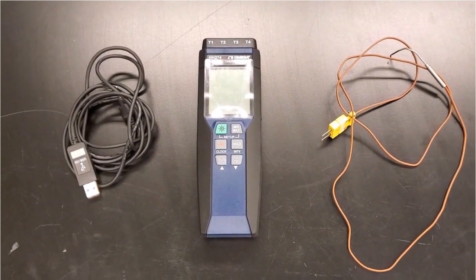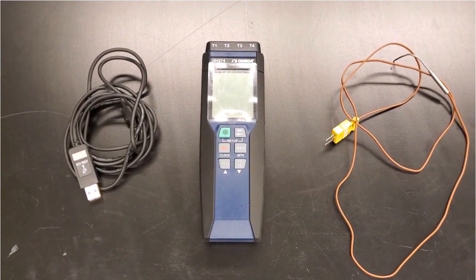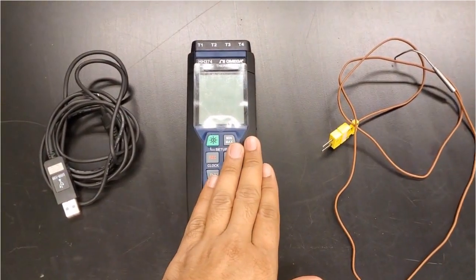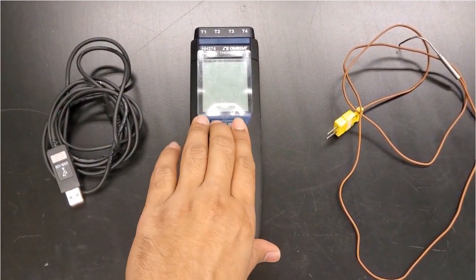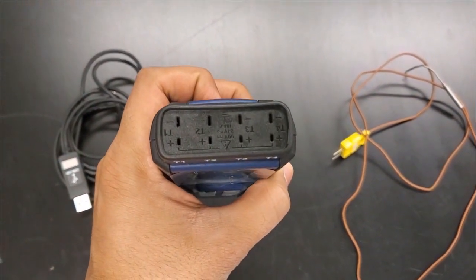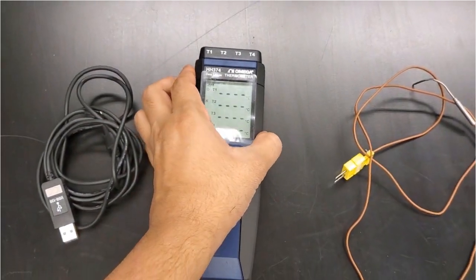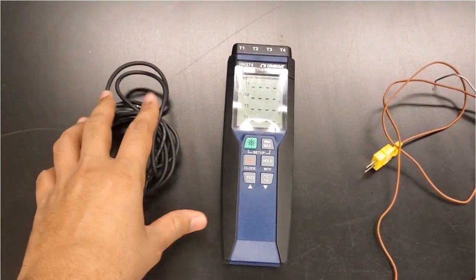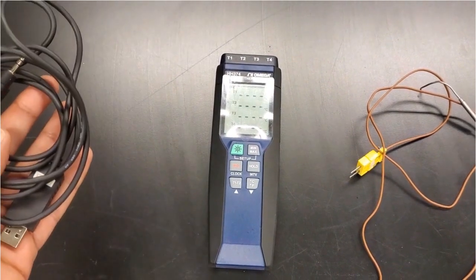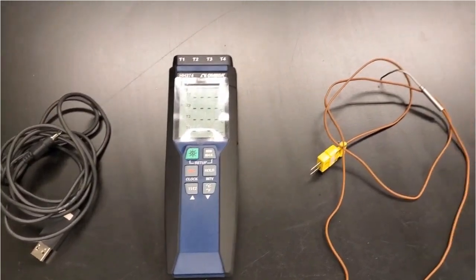This is the thermometer that we use in the AML lab to measure temperature values in our machining experiments, and sometimes for general purposes too. What you see now is the data logger. This is what gives us the reading, and it has 4 channels, which means we can attach 4 thermocouples at a time to this data logger, and it will give us the temperature values. That is the data cable that we use to connect the data logger to the computer and take the data that we have measured and modify it accordingly.